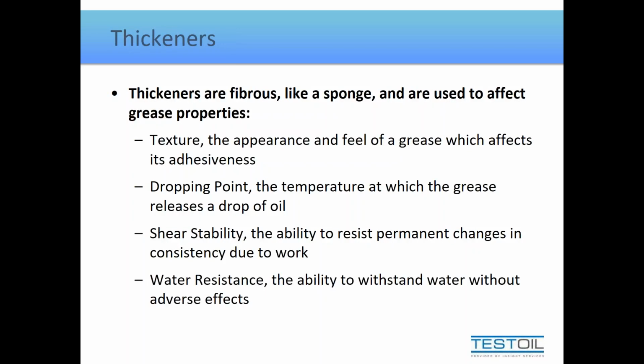Definitely there's some natural water resistance and some natural effects that may occur. So we sometimes will select completely different thickeners for a wet application than we would for a dry application. Lastly, we have pumpability, how well the grease will move. This is a greater concern when we start dealing with long runs or cold temperatures or both.